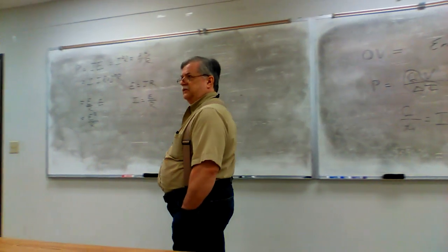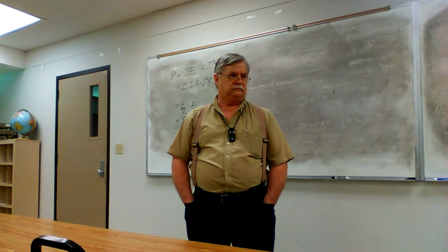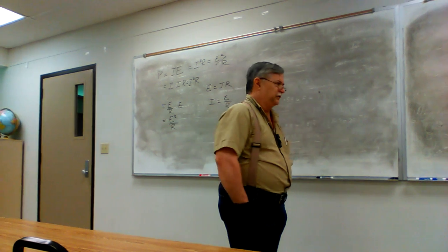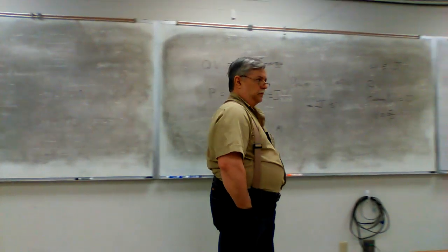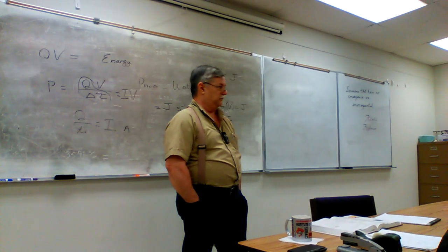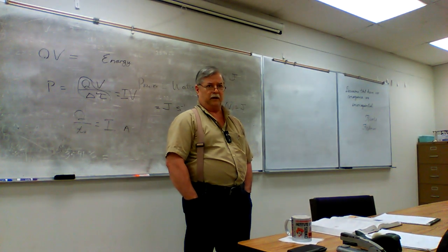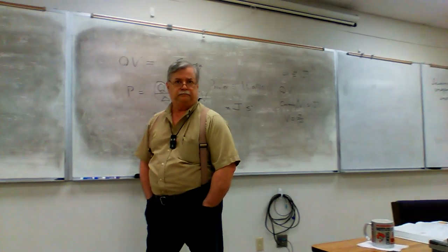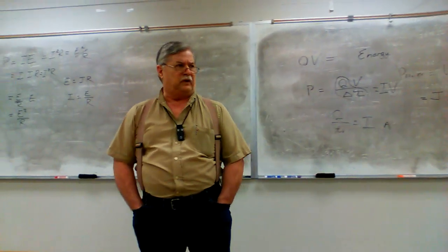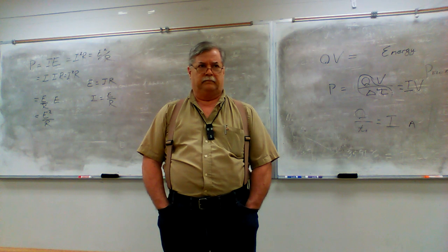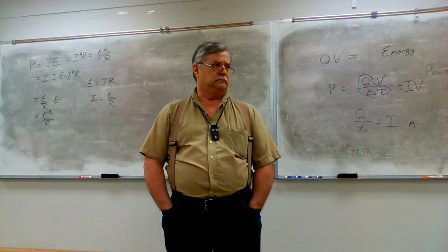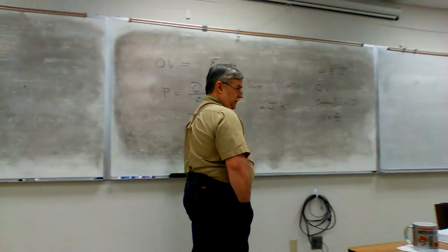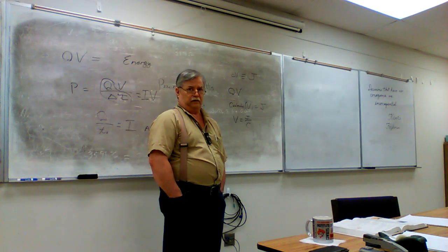So how much power is dissipated in your circuit? And what does that mean? You build a circuit. You've got a resistor that has so much current flowing through it. It's dropping so many volts across it at that current. That means it's dissipating a quarter watt, a half watt, 1 watt, whatever. What does that mean when you say that that resistor is dissipating 1 watt? It means that it is dissipating 1 joule of energy every second.